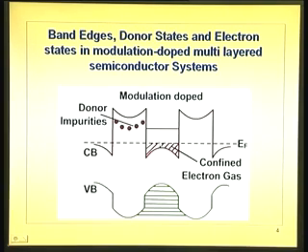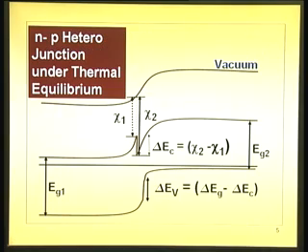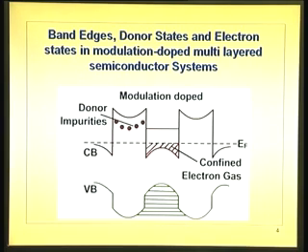This is just I showed undoped, all the layers uniformly doped, N type, and next one alternate layers doped, that is selectively doping this portion. These will be layers arranged one over the other. On the top of the bottommost layer will be that, you can go on to the top. Okay. So, the energy band diagram is drawn horizontally, but layers are one over the other. Okay. So, you grow layer after layer, one layer you dope, the next layer aluminum gallium arsenide, dope it.